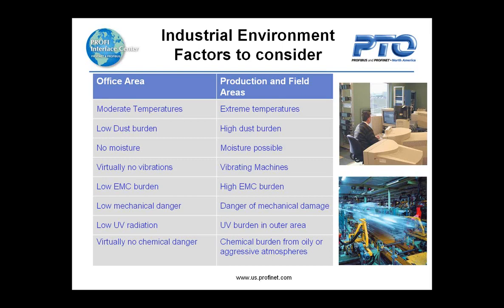Vibrating machines. We have high noise probably. We maybe have some high frequency drives or something we're running on the network with some pretty heavy-duty motors, and those kinds of things can induce noise maybe even into the system, so we have to be careful. We probably also have moving things. We have danger of something getting damaged, maybe if something hits it, so we need to be careful. Also, the cabling and the things we need to care about, because we probably have some chemicals floating around out there that we could get on the cable, the Ethernet cable, so we need to think about those types of things.